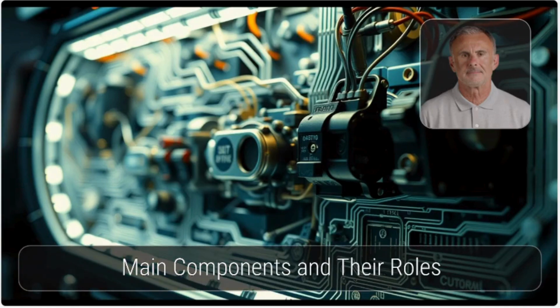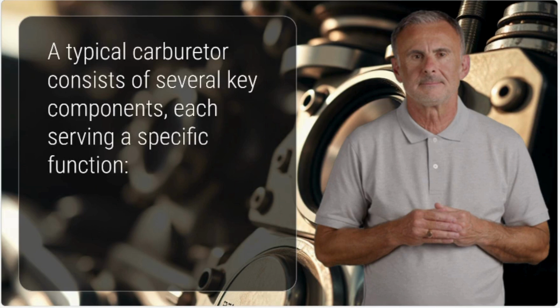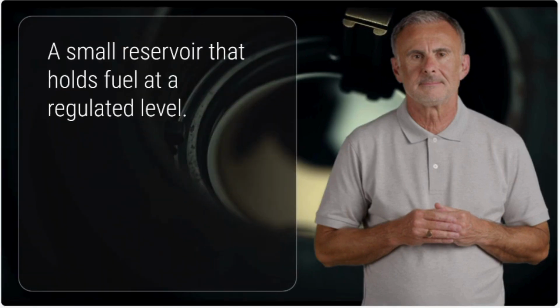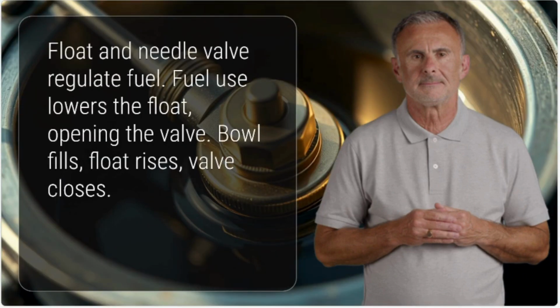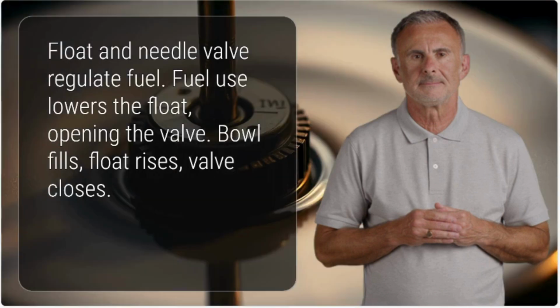Main components and their roles. A typical carburetor consists of several key components, each serving a specific function. Float bowl: a small reservoir that holds fuel at a regulated level. Float and needle valve work together to control the fuel level in the float bowl. As fuel is used, the float drops, opening the needle valve to let more fuel in. Once the bowl fills, the float rises and closes the valve.